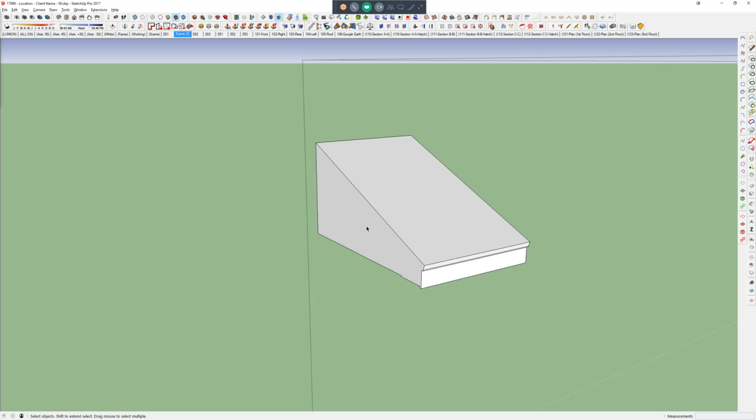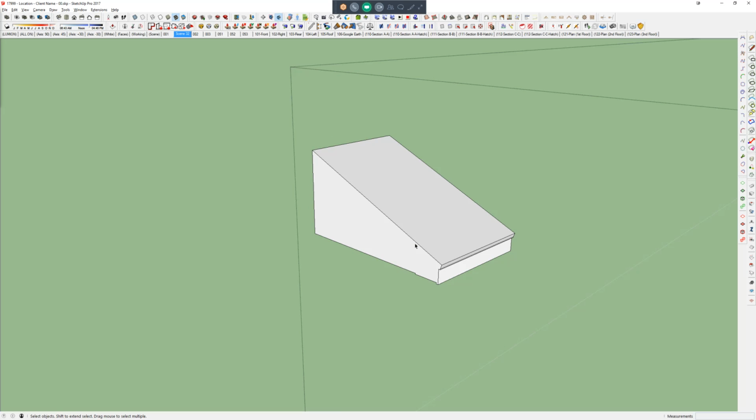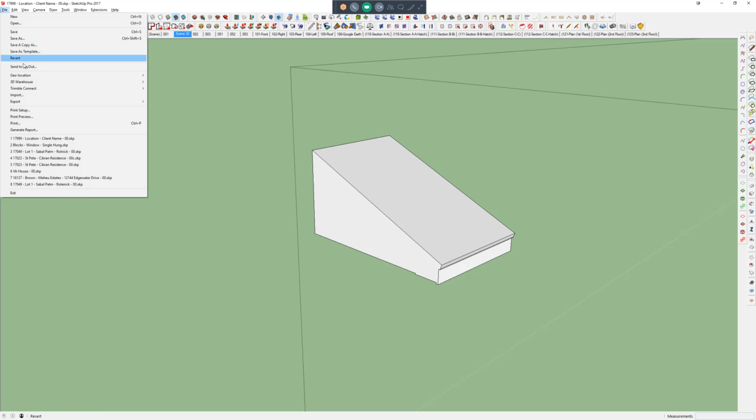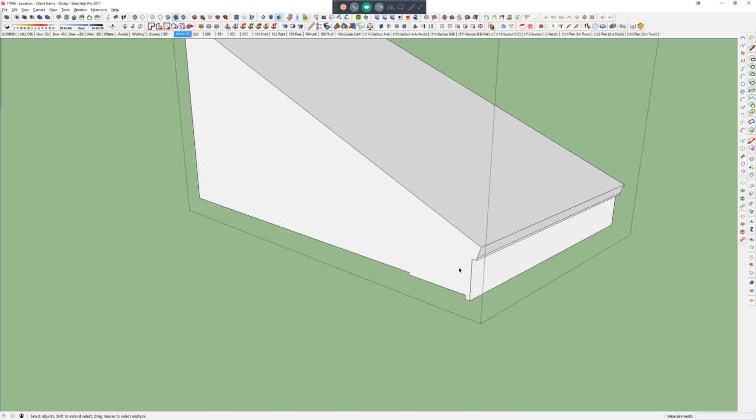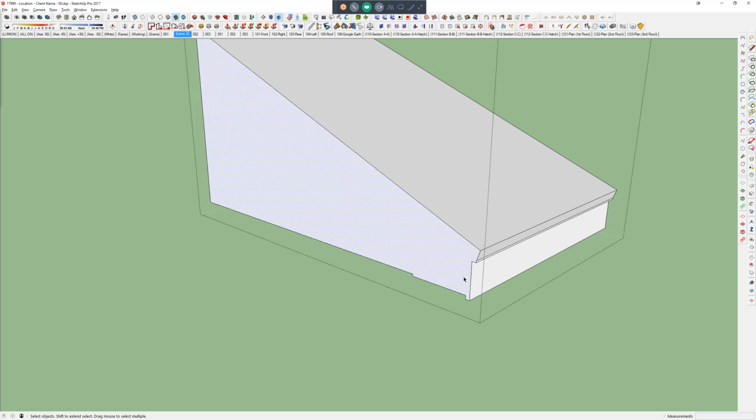You'll probably hear me talk a lot that once you start getting heavy into accurate 3D modeling, you start to understand how a building goes together, because the way I try to model everything is literally how it's built, and that's how we're going to do this gable end, instead of the quick and dirty way. And there's no problem with this if you're in a hurry.